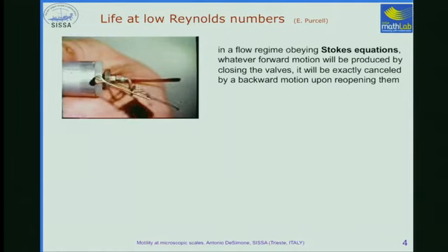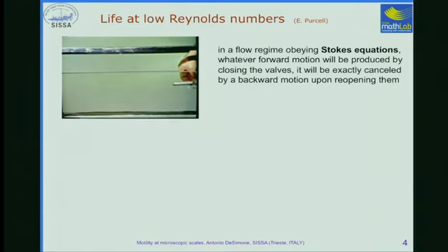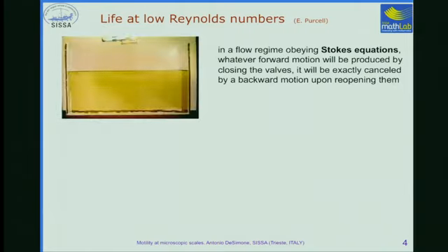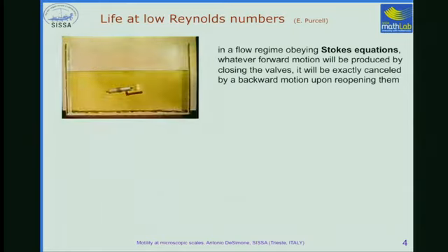So it's more a rudder, but it's a way of propulsion that works by doing this. It works at high Reynolds number, so in water. But if you decrease the Reynolds number by ramping up the viscosity, you go nowhere on average. Okay? So there is some motion, but no net motion on average. Okay? And the reason is the fact that the type of shape changes that you're exploiting are too poor. Okay? And as you will see, this leads to no net motion.